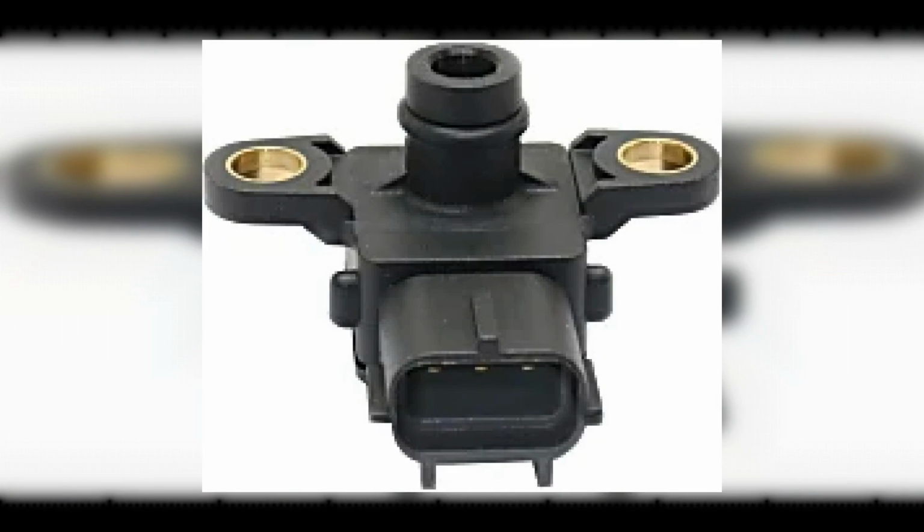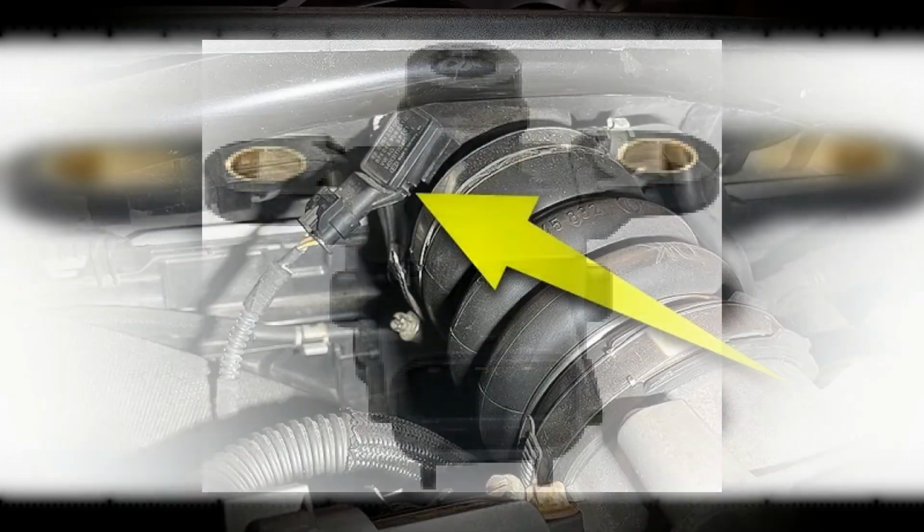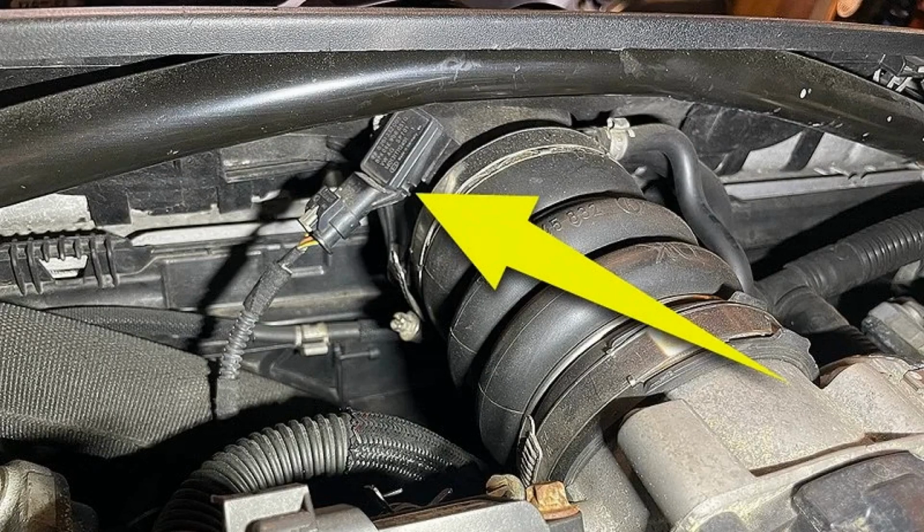The PCM regularly tests the inputs involved by comparing sensor readings. The reading of each sensor must match the equivalent data on the other sensors, otherwise the PCM may record a P0068 code. The readings from these sensors guide the PCM as it defines how long the fuel injectors remain open and when the spark plugs fire to ignite the resulting air-fuel mixture inside the engine. It will modify these variables to obtain the most efficient fuel-air ratio. Note, although the Society of Automotive Engineers, SAE, has established the generic code P0068, the vehicle manufacturer may propose a different interpretation of the code.